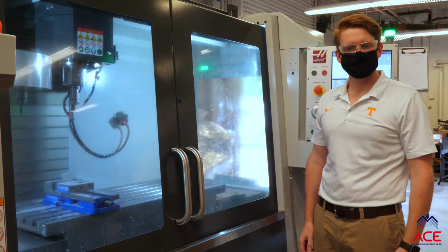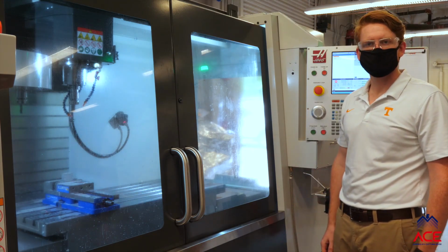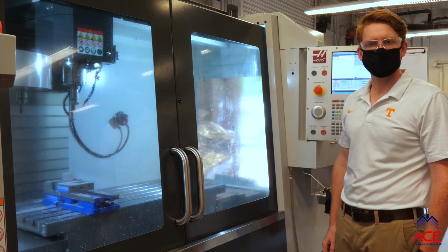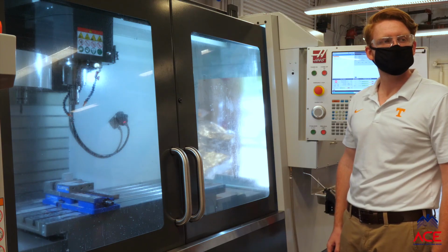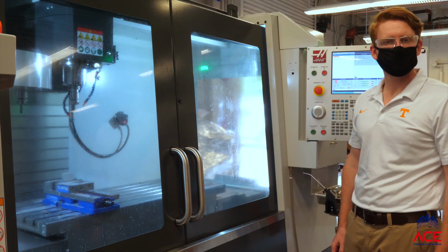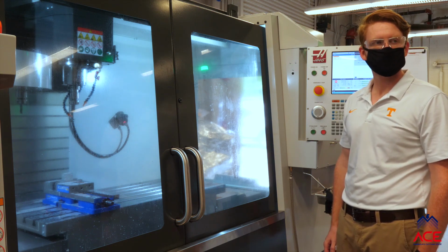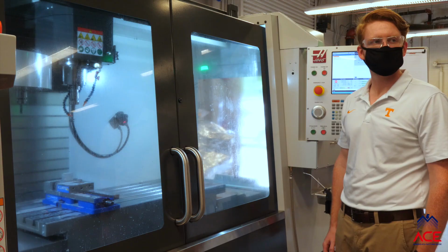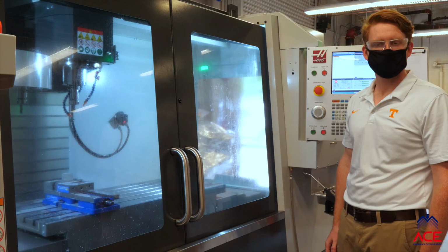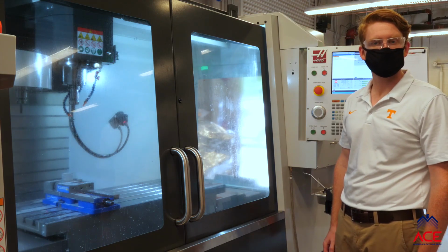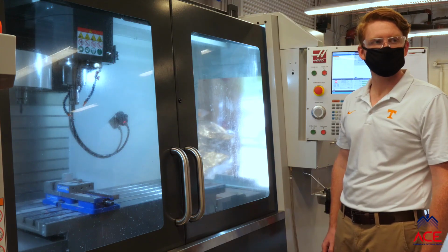So now we're ready to begin our cutting tests. And as I mentioned, we'll do 1 cut for unstable or chatter, and 1 cut for stable machining using the parameters that we already identified using our stability map and the MillMax dashboard. So what Greg's going to do is first complete a tool change to move the tool that we already measured into the spindle. He's going to adjust the coolant lines so that we have the coolant pointed at the tool, and then complete our first cutting test, which is the chatter demonstration. Greg?